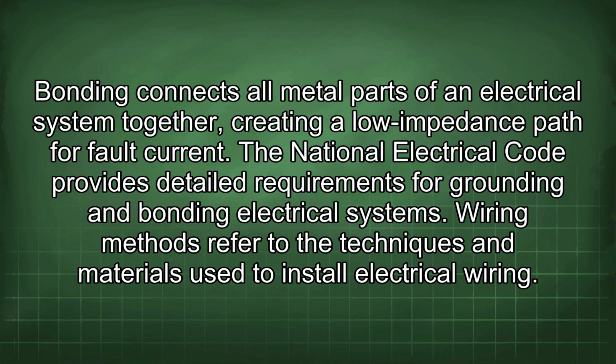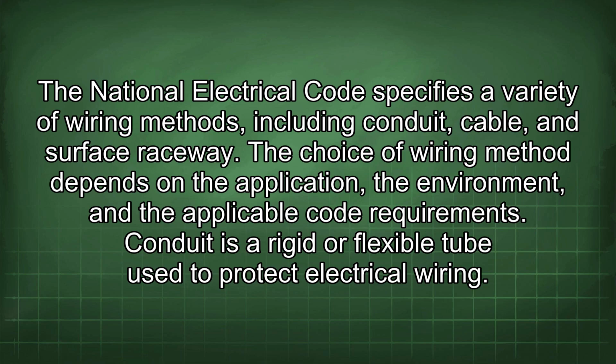Wiring methods refer to the techniques and materials used to install electrical wiring. The National Electrical Code specifies a variety of wiring methods, including conduit, cable, and surface raceway. The choice of wiring method depends on the application, the environment, and the applicable code requirements.